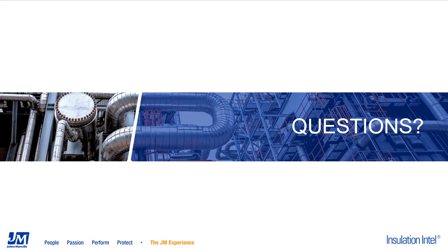The next question is, I would like to know what your highest temperature rated fiberglass is and how high of a temperature. I can go ahead and address that. We typically don't include fiberglass in our industrial portfolio because it doesn't go as high as our other industrial products. So our highest rated fiberglass is called a high temperature blanket, or HTB 26 blanket, and it is rated to 1000 degrees. The majority of our fiberglass materials that are used in higher temperatures are rated to 850 degrees.